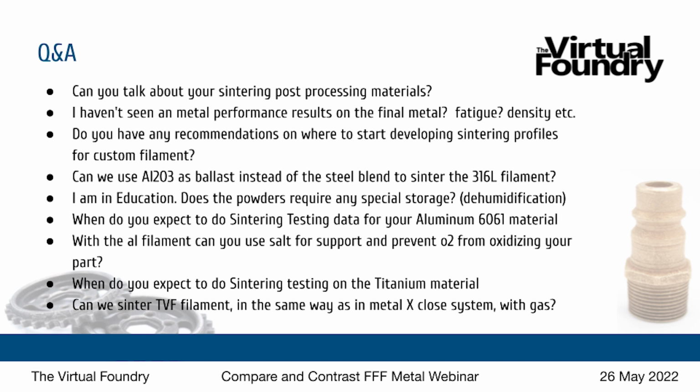Right. Part of the whole strategy of the Virtual Foundry is to simplify the sintering process and make it as low tech as possible, to make it as available to as many people as possible. So the strategy we use for mitigating oxygen is carbon. The carbon is just sacrificial. As things get warm enough, any oxygen present will react with the carbon and turn from oxygen to carbon dioxide, which is inert to the metals. So if you can come up with a different method of getting the oxygen out of the system, that will work just as well.